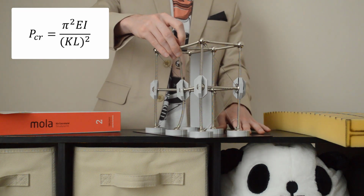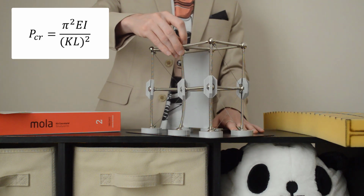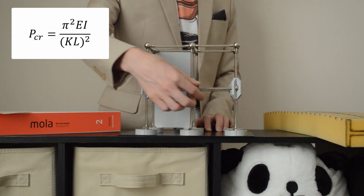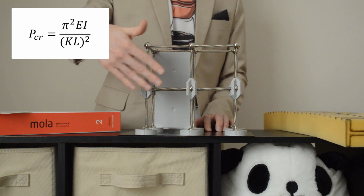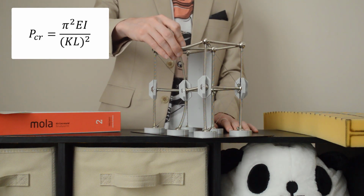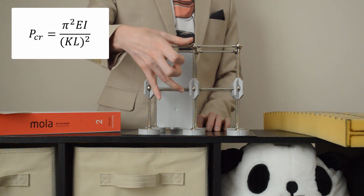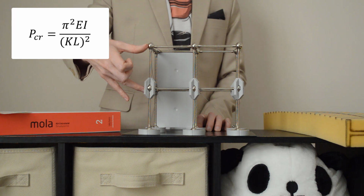Now, note that the buckling here for this column, when I push down on it, does not and cannot occur in that shape this way, because it is braced by these beams here. And in fact, it would never buckle along this front plane. It's always going to buckle in this direction, right? Because in this direction, along the front face of the building, its unsupported length is just one story height, same as this column.